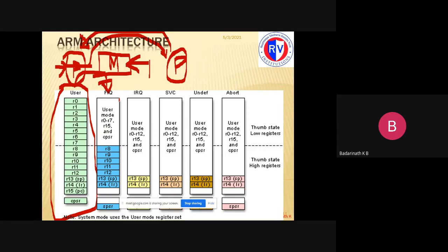So they thought it is not possible to provide a complete, separate physical set of registers just for FIQ mode. So they went for a 50-50. 50-50 in the sense that I cannot provide a complete R0 to R12 replacement, so let me provide at least half of the registers, so that efficiency can improve by 50 percent.